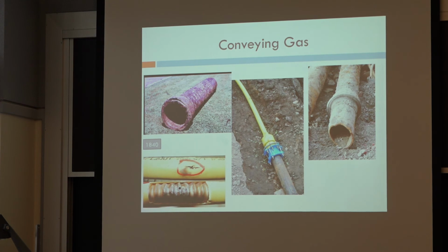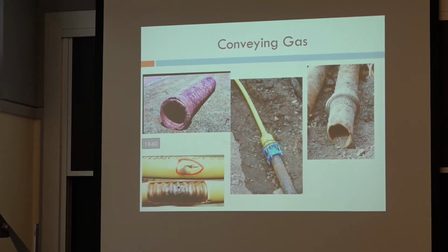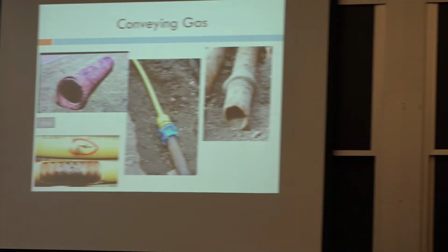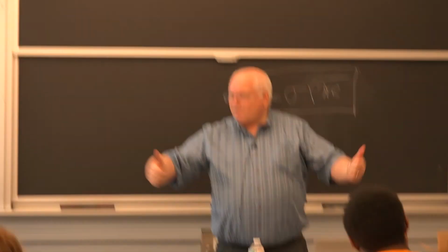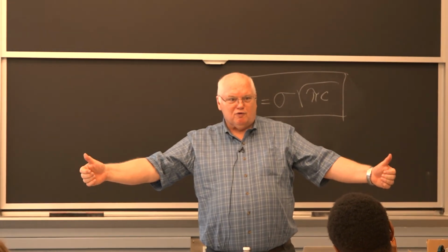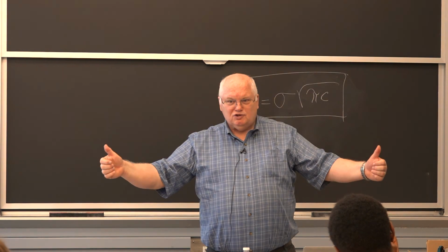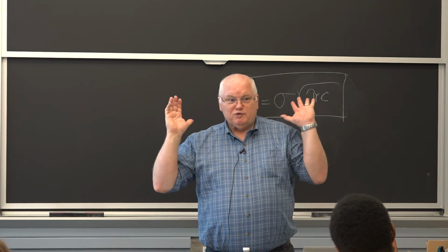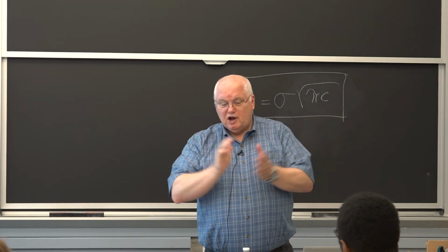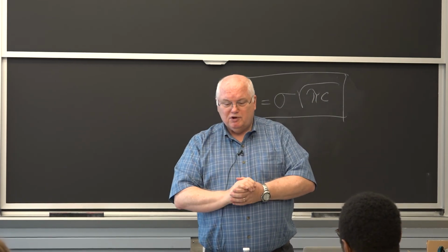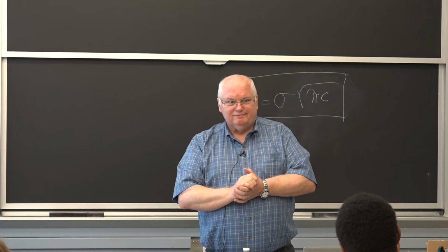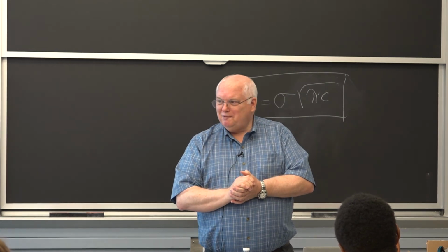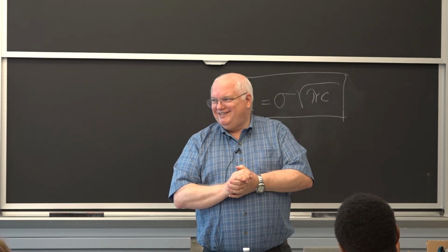Because in New York City, when you dig up the road to replace the pipe that broke, you're going to disturb the pipe on either side. And you don't want to have to dig up a long section of road in New York City, because it tends to disturb traffic for too long. And it helps me a lot. When I get a job in New York City, they say we had a water pipe burst. I ask, when was the last one in that area? And usually you find there was one about 3 to 5 years earlier.